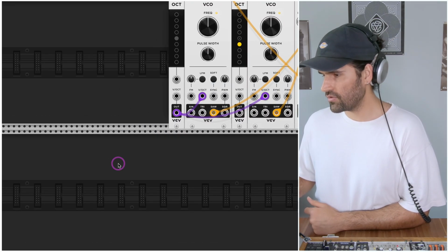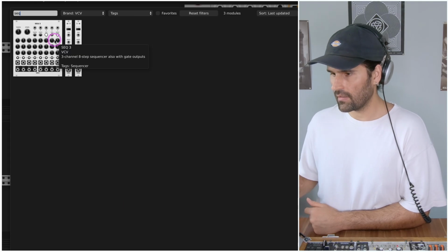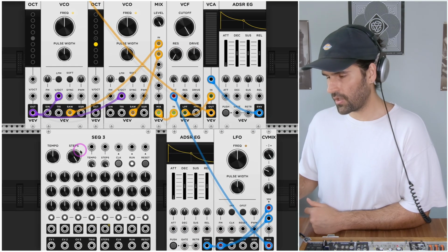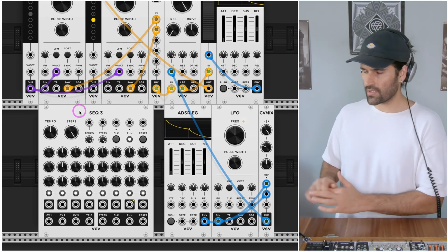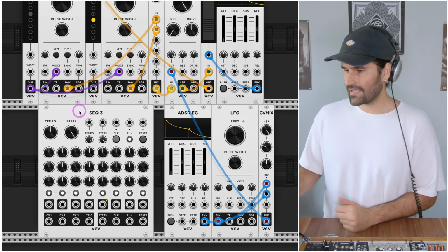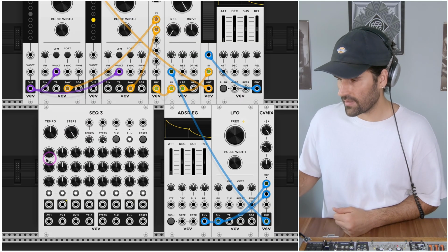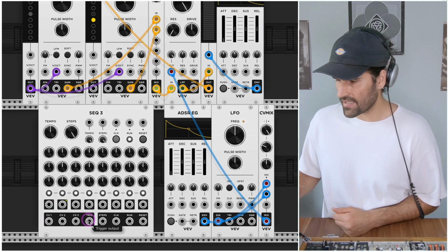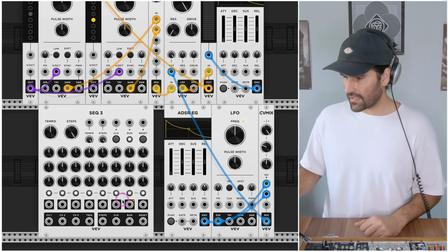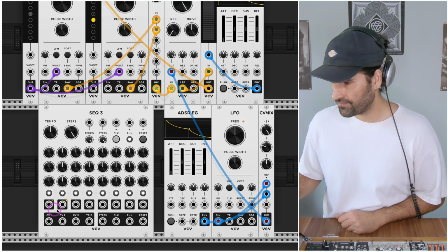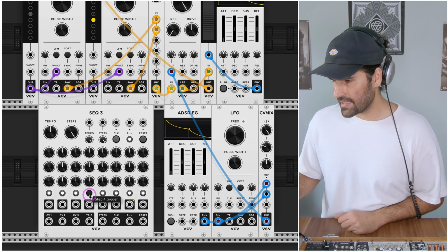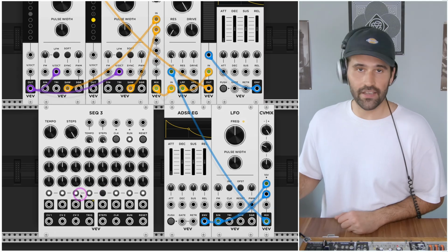So for this one, I will use a sequencer. Because the good thing about Modular is that you can use sequencers. So let me explain to you what is happening here in this sequencer. This sequencer has 3 rows. As you see, the first row, 8 steps, the second row, and the third row. The CV outputs are given here, CV 1 to 3, and there is a trig input. So take a look at this yellow LED. It's telling us where the sequencer is going right now. And with these white LEDs, we can turn on or off a step.